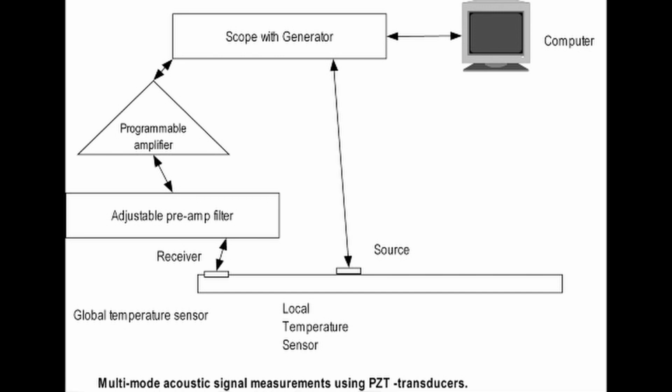This detector is used in structures that support specific acoustic modes of guided wave propagation, and a careful interpretation of the propagation modes is required. The signal recognizes distinct areas from known structural features such as the ends of the pipe, welded joints, stands, clamps, and also unknown structural features such as corrosion.